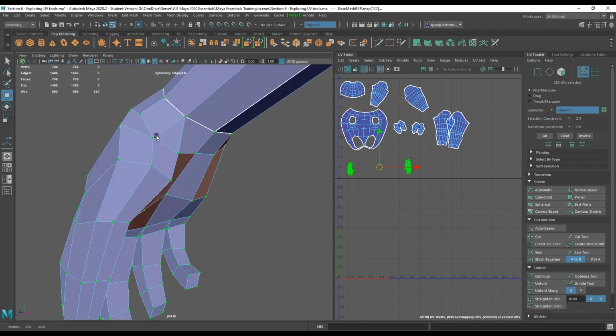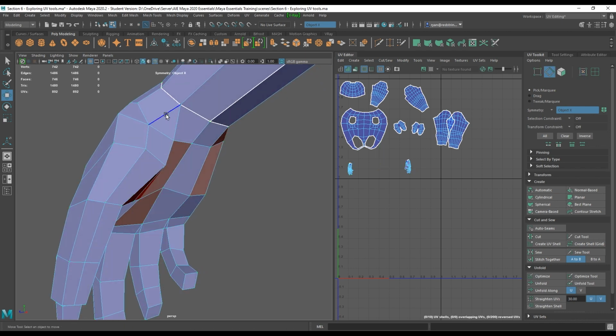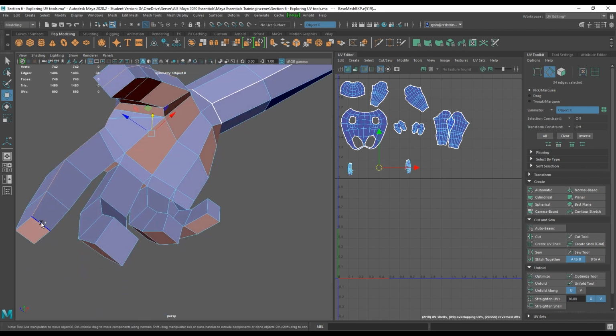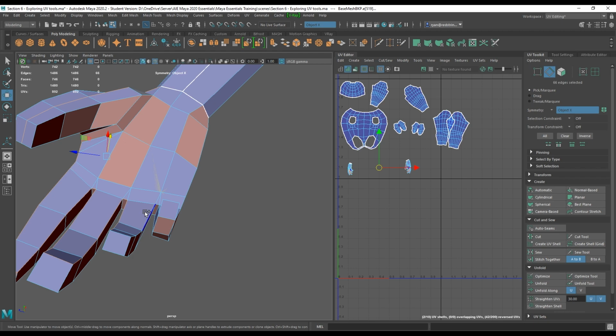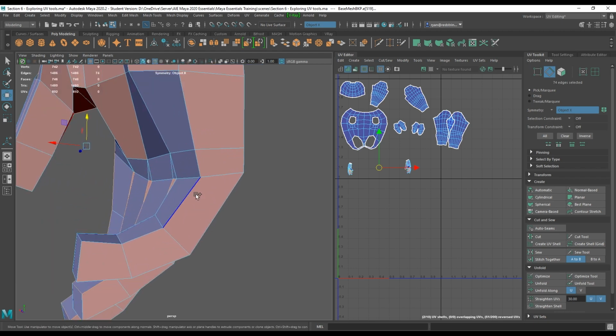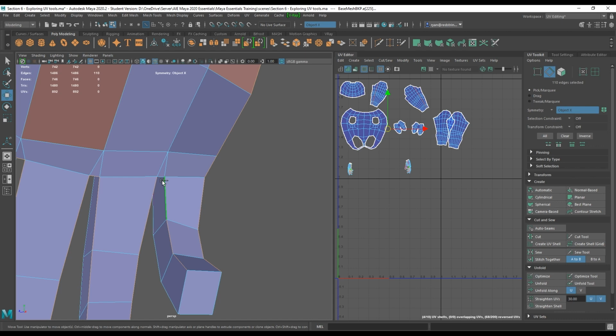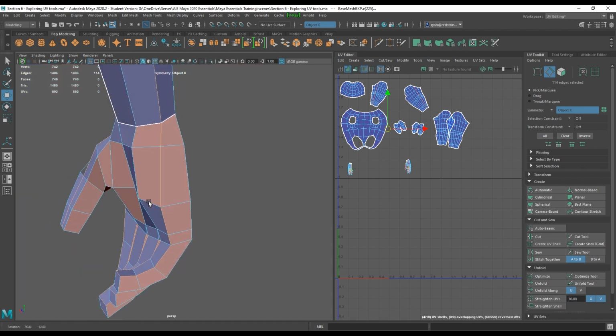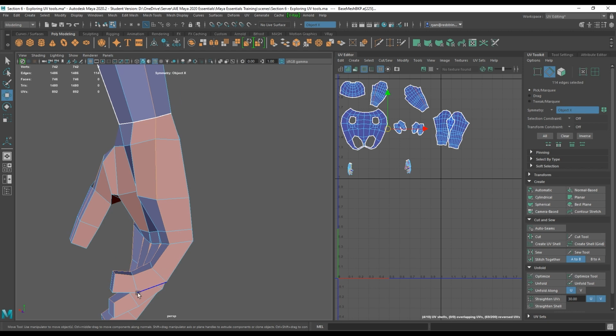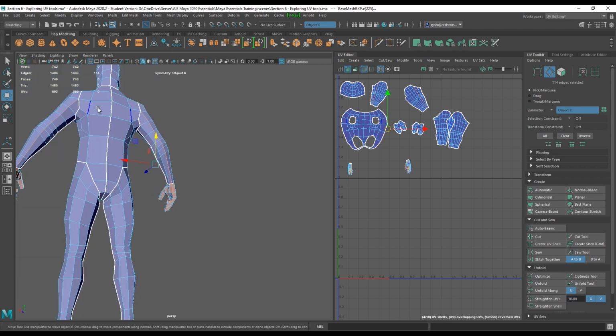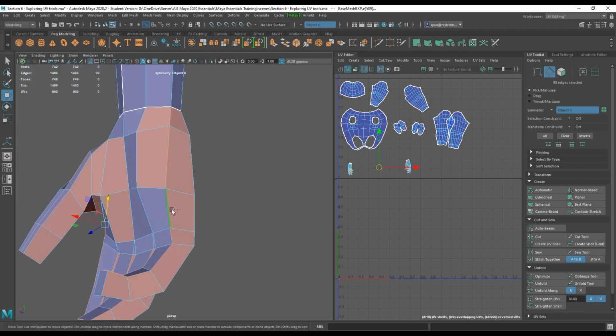So I would like the center of the thumb to wrap out. So I'm going to go edge mode, click that edge, double click, see how far it goes up until there, double click, goes up until there, there. Yeah, now I'm just going through the rigmarole of selecting these edges where I would like to do my cut, and it goes. Now I have an option of splitting the hand in two as well, so the top and bottom are on each a different island, but I would prefer to have a hand as an island. So here by the palm area, I am just gonna deselect these guys so they stay connected there. I'm gonna go cut, and now let's go and see what we get.